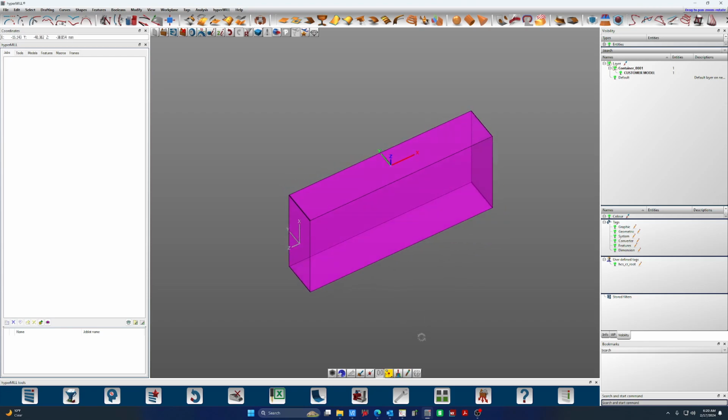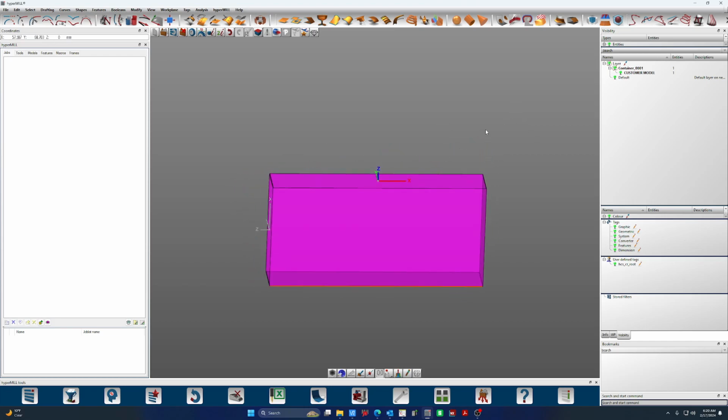For the times I don't, you deactivate that, and that means, for instance, if we were going to offset this curve here, it might just offset it in 3D space relative to the ISOs of this surface versus automatically happening on the work plane that we're on. And we'll find, as soon as we get into some programming, it'll become immediately apparent why that's important.